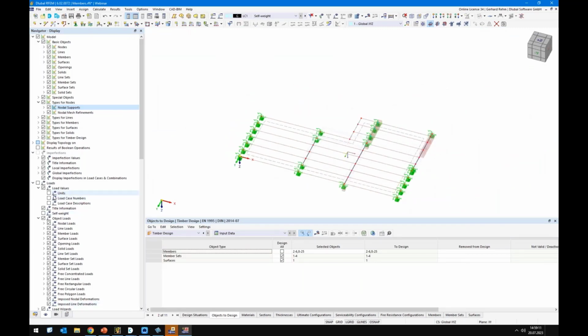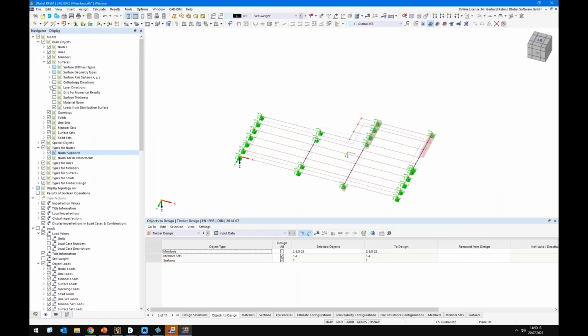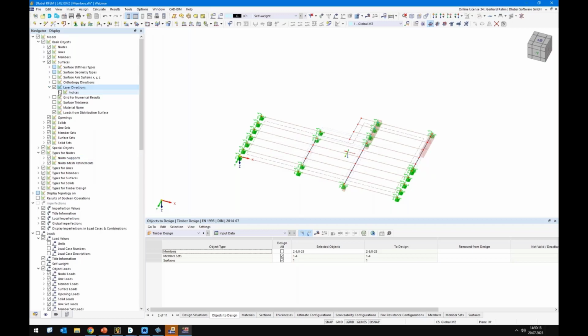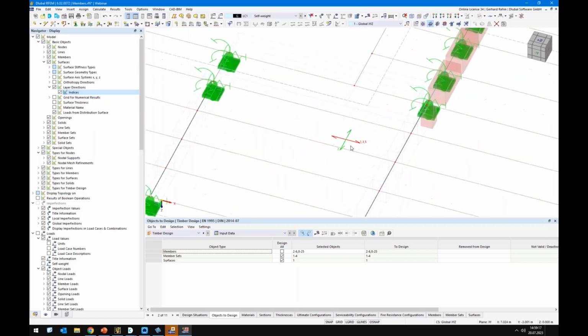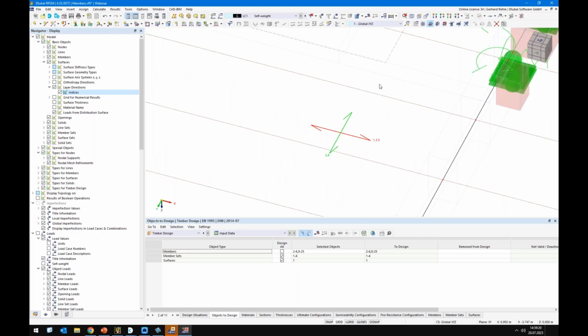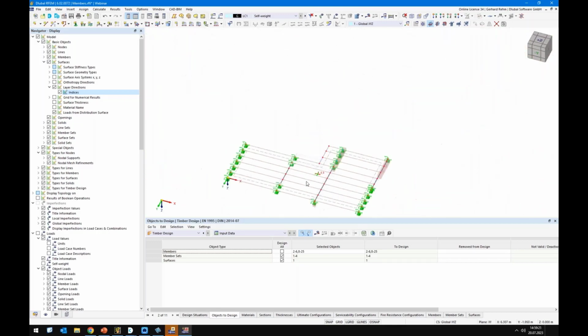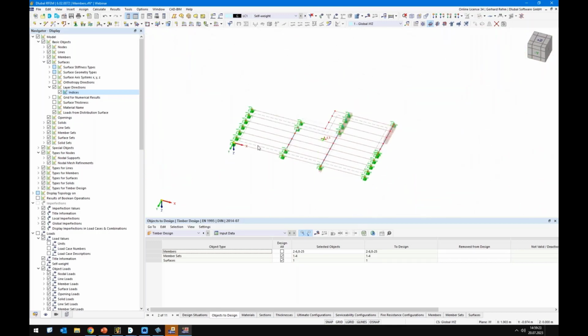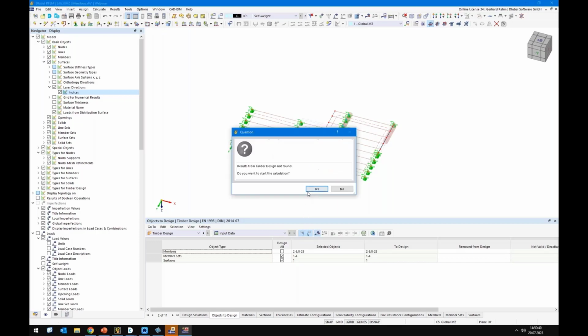We can check the orientations again for this surface in X and Y direction. So layer 1, 3, and 5 go in this direction, and layer 2 and 4 in this direction. So it's okay. Here it's the same because of the bending moment. Of course, the elements are larger. Maybe it's worth it to model the surface, to split the model at every, in this case, 125 centimeters, and add a line hinge in between. So for simplification, I leave this for now.